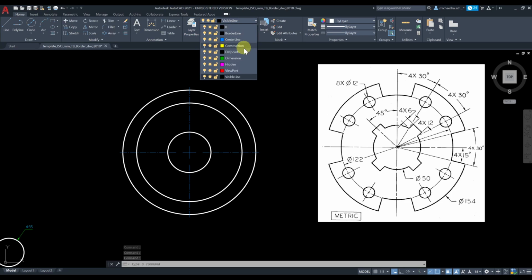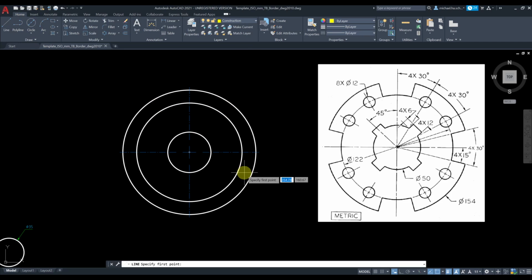Okay, let's change the current layer to construction. I'm gonna draw a line from the center somewhere here. You can press F8 to draw it horizontally, or if it tracks the center, it'll be horizontal. Press enter. Okay. Now, as I talked about my strategy, I'm gonna array this against this base point with a total of 6. When you do that, with the angle in between of 15 degrees, you're gonna see what happens.